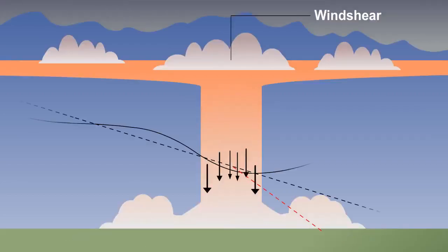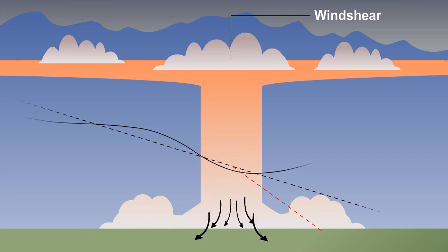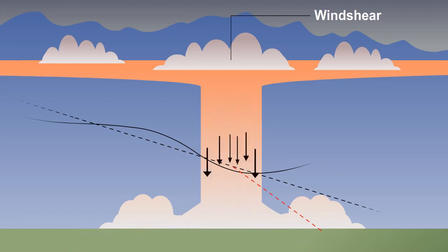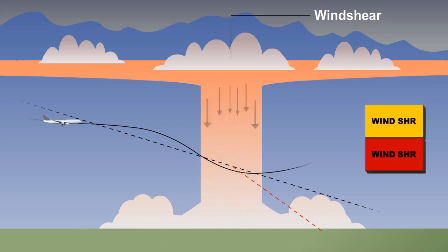Mode 7, which has priority over all other modes, provides the crew with visual and aural alerts and warnings when entering a potential wind shear area. To achieve this, it requires inputs from ground speed, airspeed, barometric height, rate of descent, and radio altitude. The system reacts to the onset of wind shear conditions. This allows crews to initiate the escape maneuvers earlier, giving them a greater chance of avoiding a potential accident.